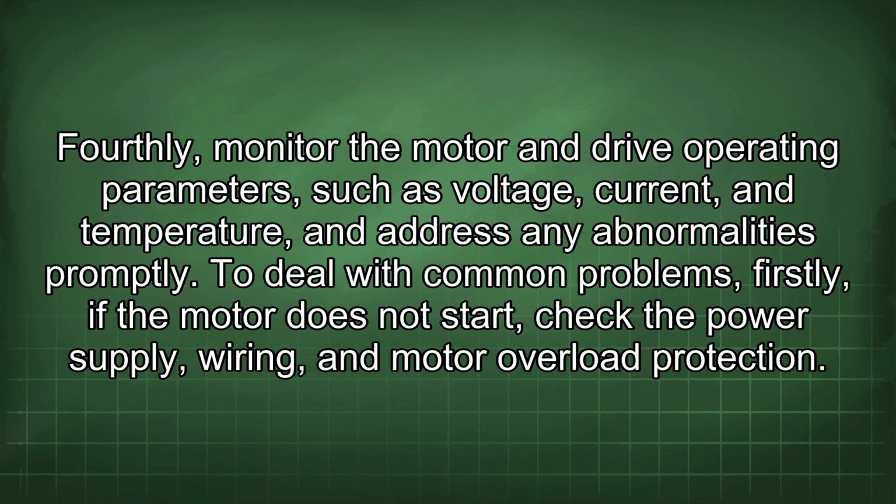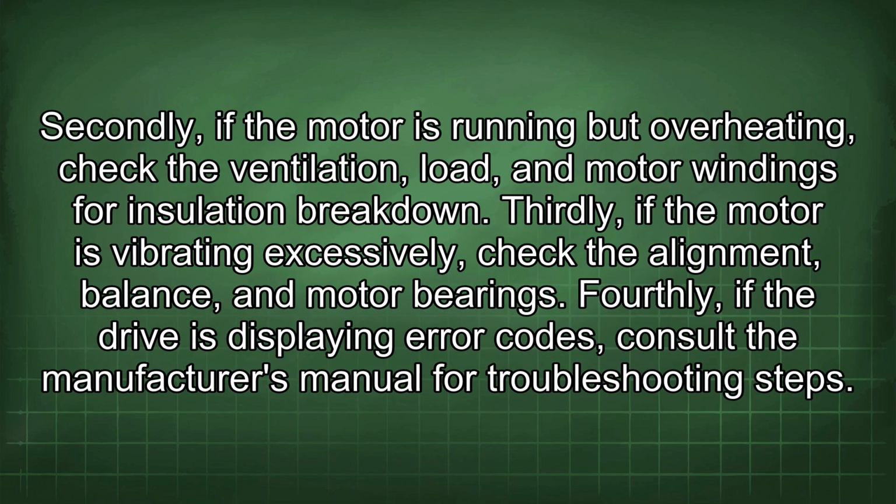To deal with common problems, firstly, if the motor does not start, check the power supply, wiring, and motor overload protection. Secondly, if the motor is running but overheating, check the ventilation, load, and motor windings for insulation breakdown. Thirdly, if the motor is vibrating excessively, check the alignment, balance, and motor bearings. Fourthly, if the drive is displaying error codes, consult the manufacturer's manual for troubleshooting steps.